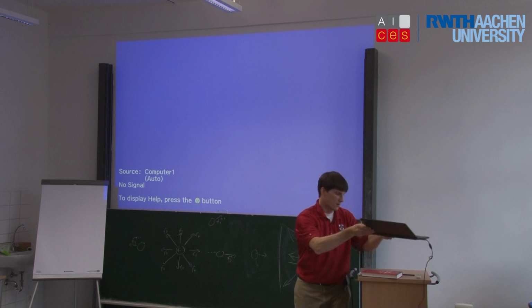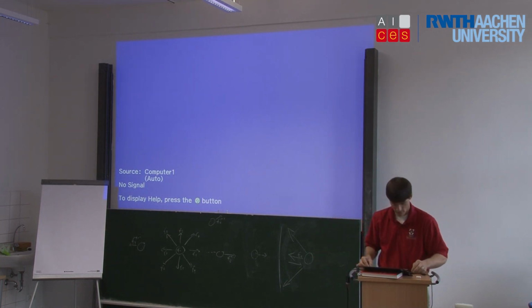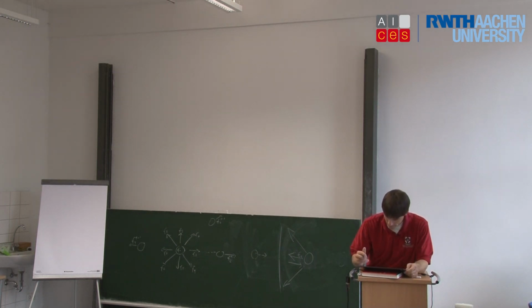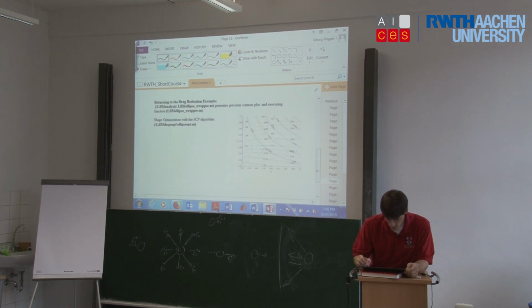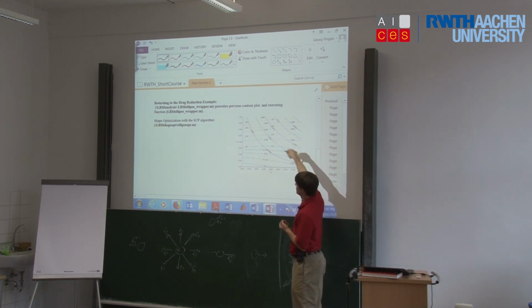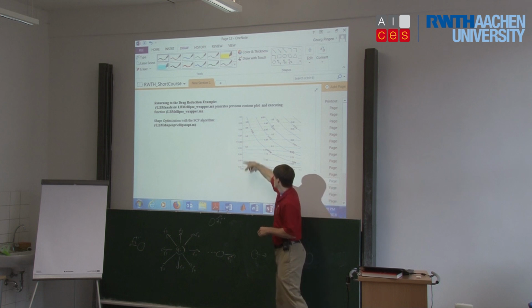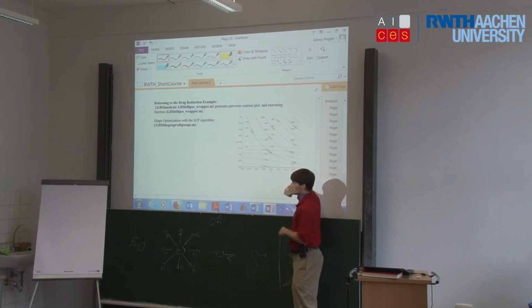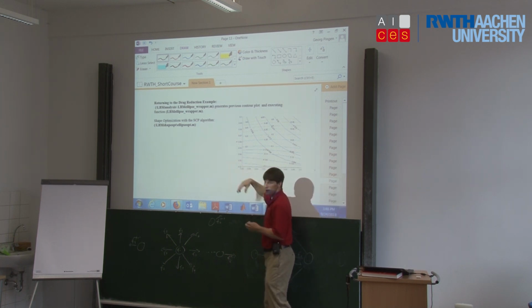So let's pull up my slides again. So we had, if we run the program LBM analysis, LBM ellipse wrapper, that gives us this contour plot, which is a contour plot using the Lattice-Boltzmann method of varying A and B, drawing the contours for the volume, and then drawing contour lines for the drag. And we would find that the minimum drag would be right here at this corner, which is at B equal to 0.1 and at A somewhere smaller than 0.03. And those are the results that we just found.